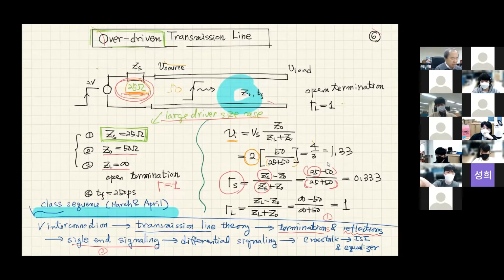As an example of study, I'm going to give you a special case of single-end termination that is called SSTL. Usually SSTL is used as the I/O scheme between CPU and memory. The single-end signaling scheme has certain disadvantages. Because our interconnections are very three-dimensional, sometimes we will see impedance discontinuities. If we have impedance discontinuities, we will suffer reflections that, in most cases, are not what we wanted.